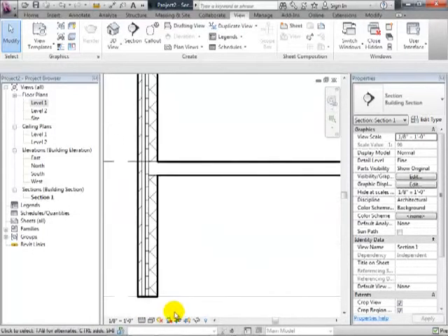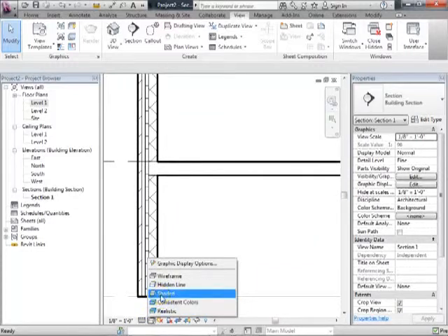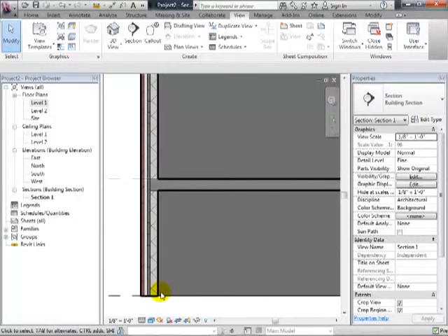Let's go ahead and talk about the difference between what's going on my screen and your screen. On my screen, you'll notice that I actually have the floor cutting out and intersecting. So the floor is coming out to the outer structural layer. The concrete block is coming up, so the wood joists are in here. Then we have the brick veneer, the wood, the air and the insulation all on the outside. It's really creating something pretty close to the accurate detail. So you'd like to have that happen, having it be as close as possible to what you want.